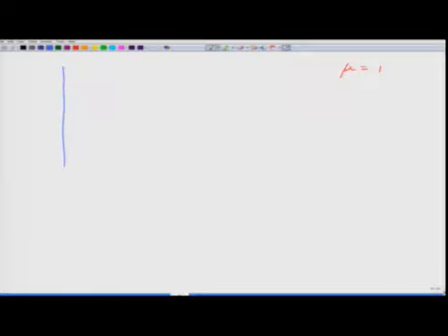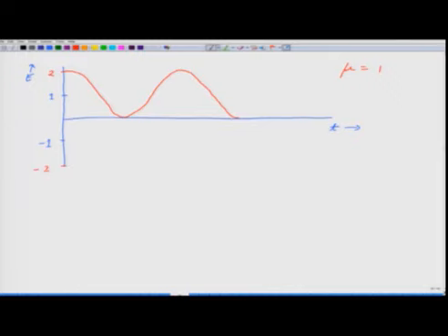Once again we draw on the y axis the electric field, x axis as time, and 1 is the amplitude of the carrier wave. On the negative side it is -1, and 1 is also the amplitude of our modulating wave. So the maximum will be +2 here and -2 here, and our modulating wave will now have maxima at 2 and minima at 0. So it will behave like this, and from the negative side it will come here.